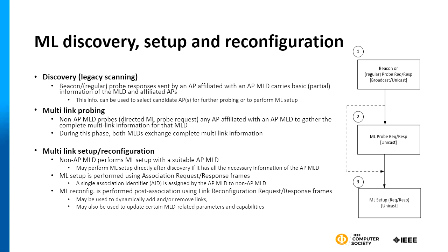Given that this information is often partial in the passive scanning phase, we also have an active scanning phase, which is based on probing. During this phase, the non-AP MLD can additionally probe any of the APs affiliated with an AP MLD to gather the complete multi-link information for that AP MLD. This includes, of course, capability-related parameters and also the modes of operation of that AP at that particular time.